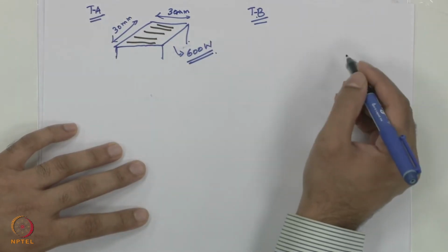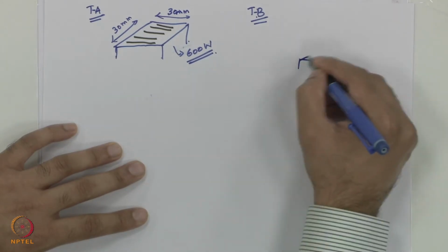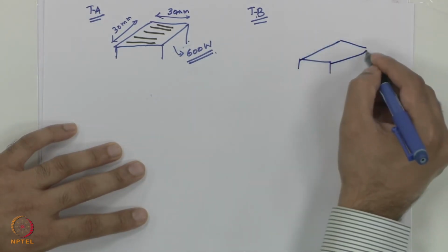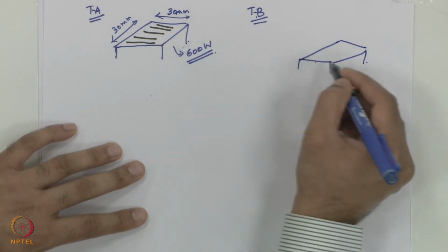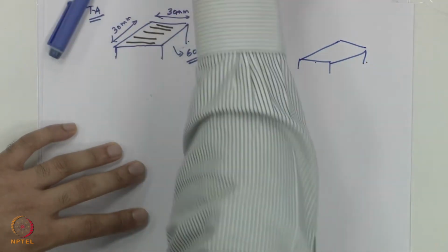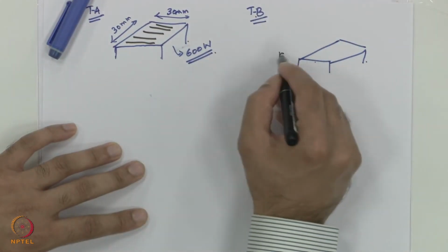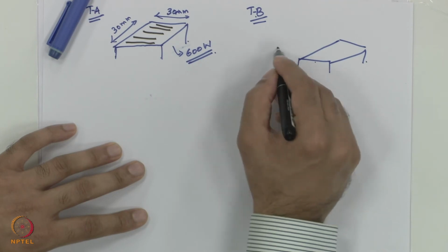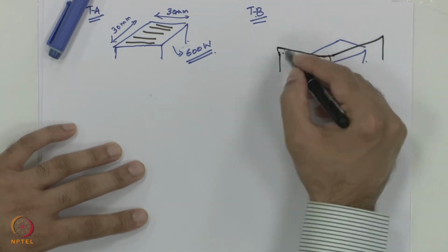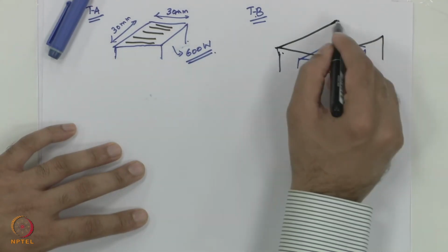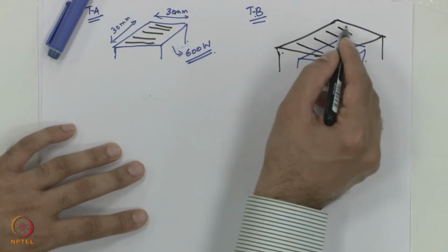So what they are suggesting is that they take a heat spreader, the same silicon device that is dissipating 600 watts, but instead now it is spread on a much larger area, and then they put down their microchannels on this.